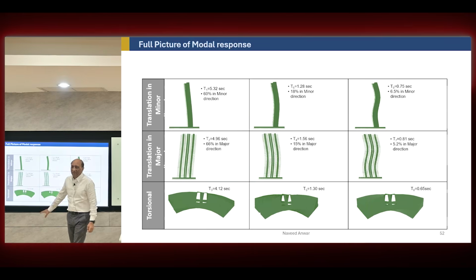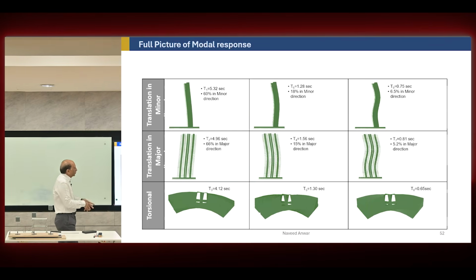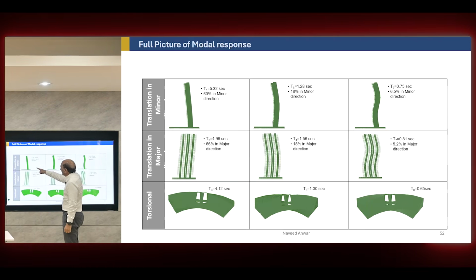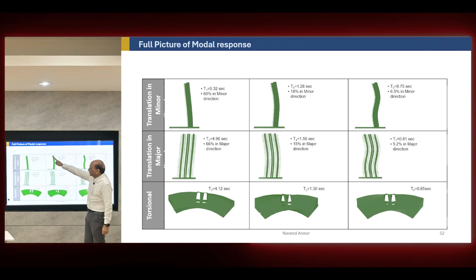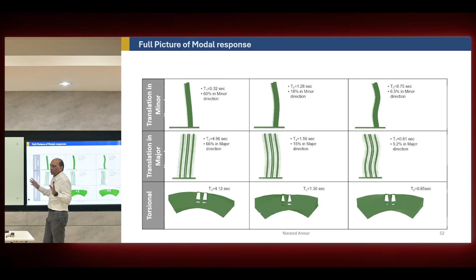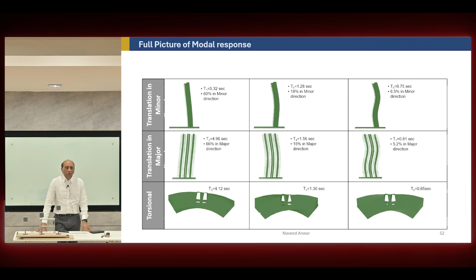So this is the table that you need to understand everything about the building. You have to look at the percentage mass participation, the order of magnitude, the order of the numbering, the difference between the 3 modes in each row, horizontally. Normally 9 modes, sometimes 12, more rows can be added, more columns can be added. So you should look into that. For a very tall building, you need more, until you get 90.